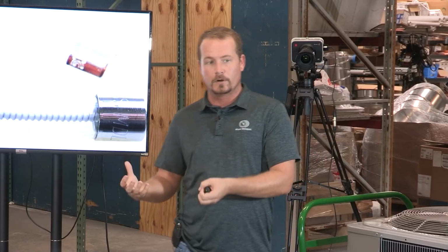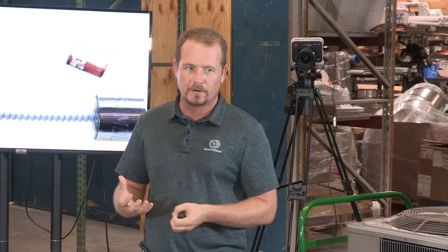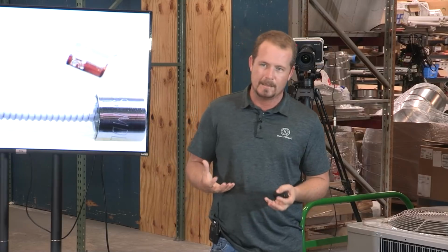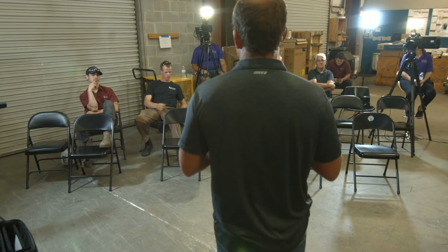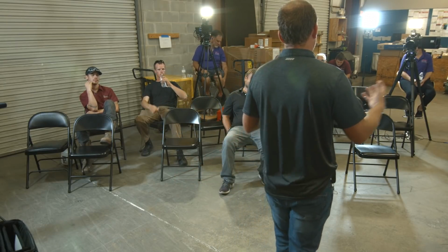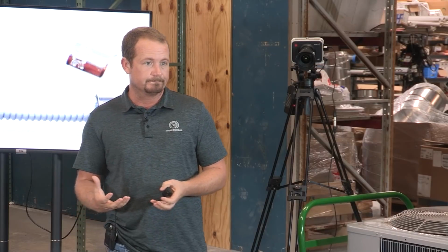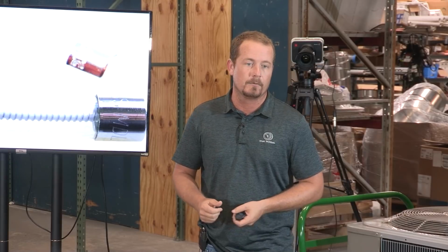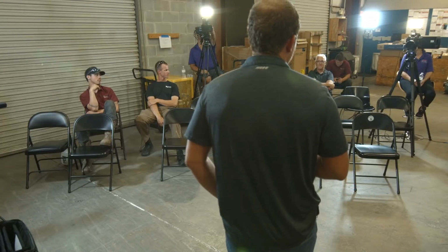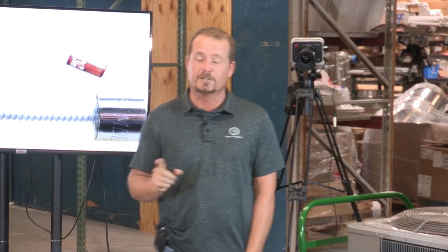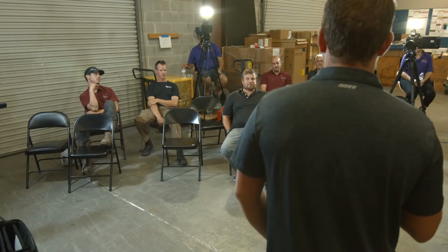But if you have something like a motor, anybody know what type of load a motor is? What's the name for that type of load? Anyone know? Sam? Inductive load. Inductive load, right. A motor is a magnetic load, and in an inductive load, the current starts out higher. So you have those start amps. And why does the current start out higher? Does anybody remember why? Why does the current start out higher in a motor? Yes, Sam? Inductive load creates its own resistance. The inductive load creates its own resistance, which is called what? Inductive resistance. Inductive reactance. Very close.